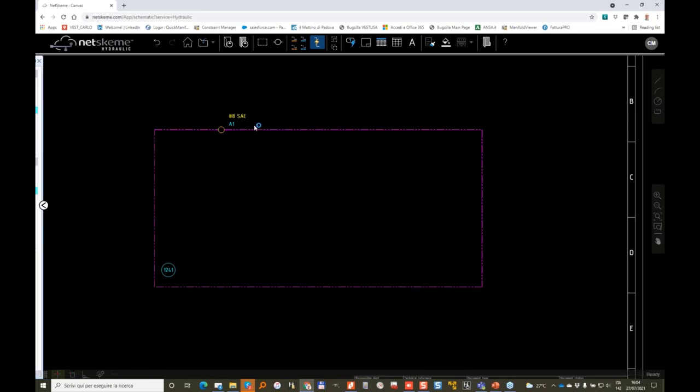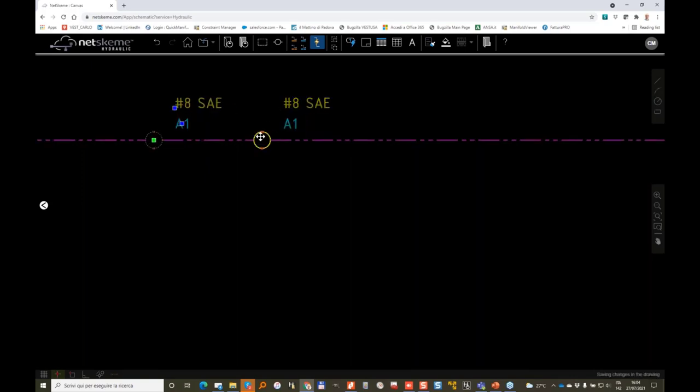Double click is more precise because you see a preview and then you can leave the symbol in the drawing. This is applicable both to external ports and to symbols. If you need to change a port name, you just double click on the text and change it.